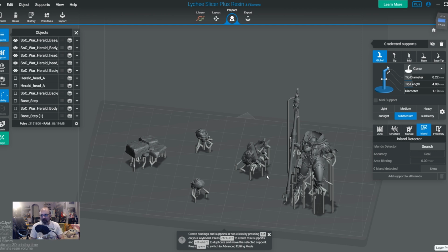So workarounds like this, also like the way I work around between Lychee and Anycubic Photon Workshop to make those files work for the different printers, like the X2, for example, and occasionally with the Mono 4, just to work around those errors. It works pretty well, and honestly, I don't have a problem with the applications in that sense. It's an extra step I have to take, which is a little annoying, but other than that, you make the workaround, and it prevents a failure, a massive one in that sense, because your print will just stop halfway through and go, nope, I'm not doing this.